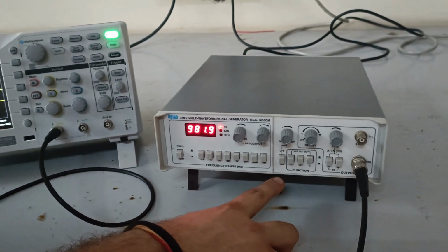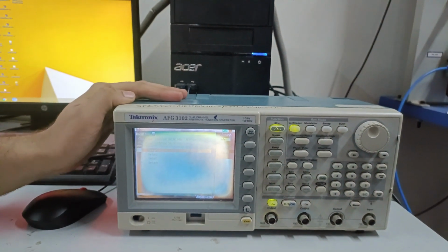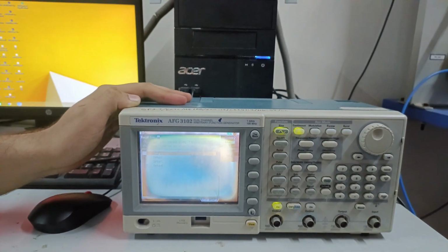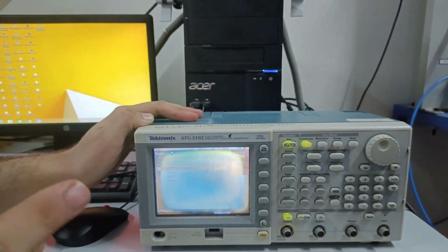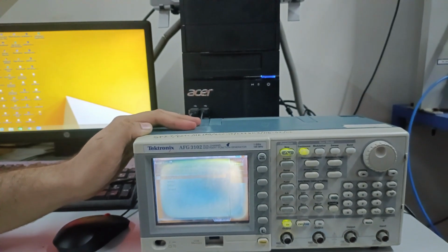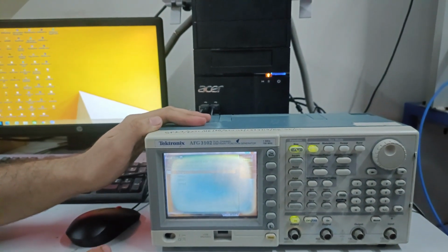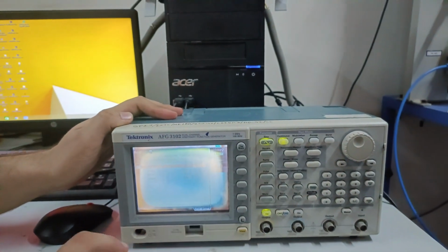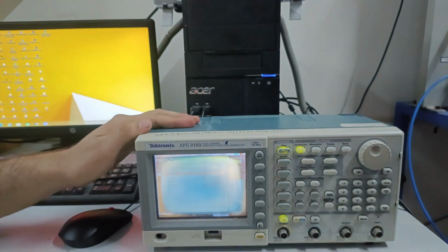Now we'll see our arbitrary function generator. This is the arbitrary function generator we are going to use. The difference between the function generator and the arbitrary function generator is that the function generator can give us only 3 different waveforms: square, sinusoidal, and triangular. It operates on a particular frequency range only, and a particular voltage range, whereas the arbitrary function generator can give us up to 1000 waveforms. There are some given waveforms, and others we can create by editing equations and then show them on the arbitrary function generator.